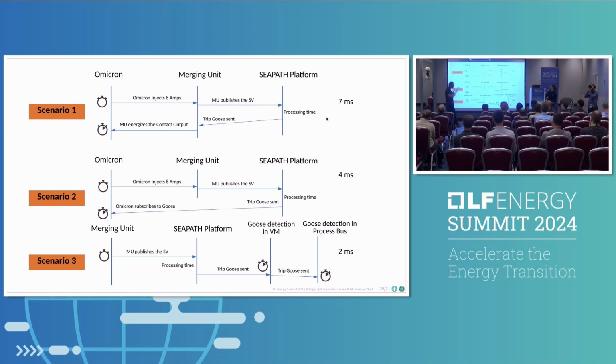It is not very important to trip in 7 milliseconds. 12 milliseconds is also okay. The most important thing is that if you repeat the test 8,000 times, you have to obtain 7 milliseconds or 12 milliseconds 8,000 times. It cannot be random. That is what we call jitter: how much the deviation is versus the nominal value.